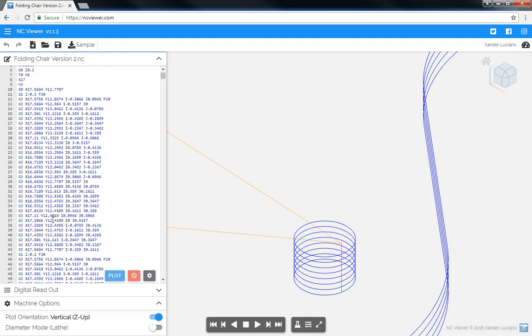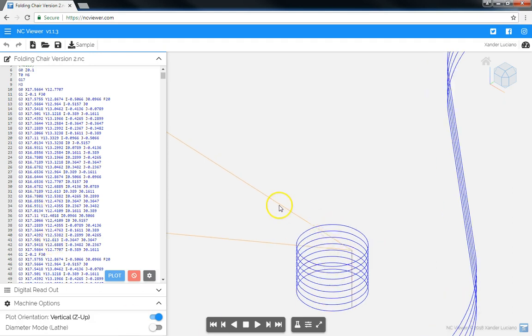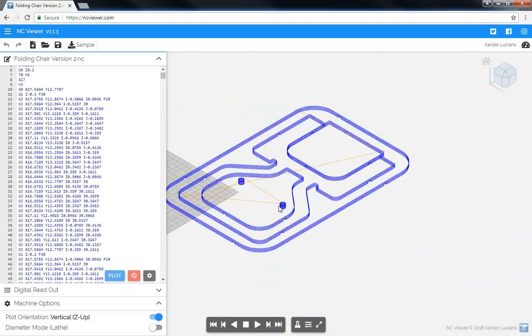The Maslow needs to drop by about 1 millimeter. So since it's lowering by 1/10 of an inch each time, that means that it's lowering by 2.5 millimeters per pass. That's not going to work out well for us, so that needs to be changed. Therefore, this G-code will not work.